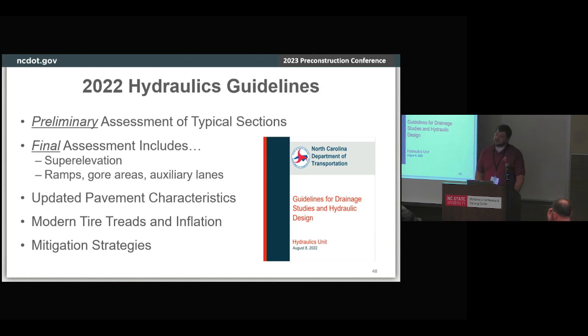So we modified it to 29 PSI, and that actually has a big impact on your hydroplaning speed. It translates to about 1 mile per hour per PSI. And that was based upon research that we got from Ong Phua, who's done a lot of hydroplaning research over the past few decades.